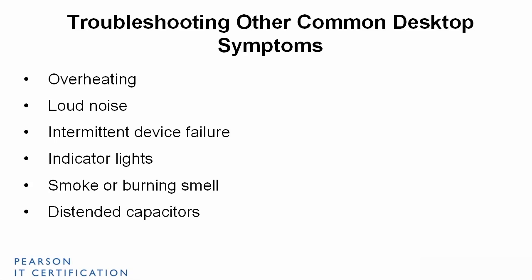And I say that's a big deal because you have to be able to solder very well. If you're not good at soldering, you probably want to just replace the motherboard. And in most cases, for the companies I've worked with, that's what they do. They don't spend the time resoldering components onto a motherboard. They'll just put a new board in. But it is possible to resolder a new capacitor onto the board.